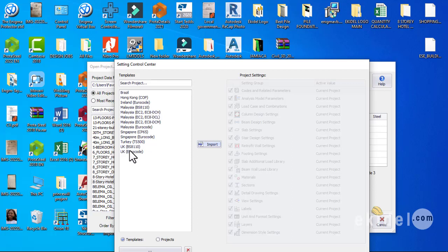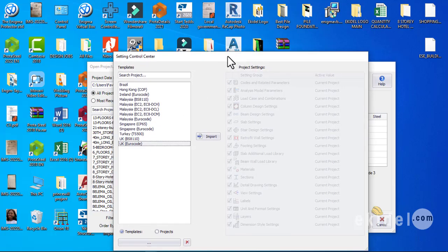And in this case right now we will be using Eurocode, so I'll go here and choose Eurocode. So depending on your country, you can choose different codes that you have here. So right now we are going to use Eurocode for this design. So I'll click on Eurocode, although you can still choose to use BS and other codes, but let me just use Eurocode here, and then I'll click on Eurocode and come here right now and click on what?